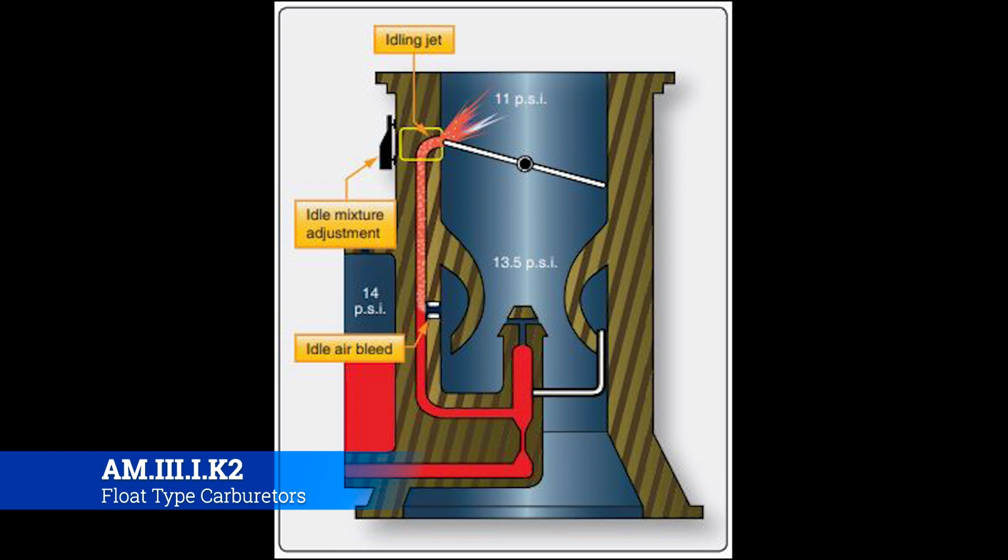So you notice on this graphic here, you have the throttle plate, the little butterfly plate that's up at the very top. It's closed, so there shouldn't be any fuel coming from the main jet into the engine, but the engine still needs to operate, still needs to stay alive and stay running, so that we can get the power back immediately without having to go through the restart procedure. And the idle jet basically is like a little channel that comes on the backside of that throttle plate, and allows fuel to come in from behind the throttle plate and keep it running. That's all it really is.